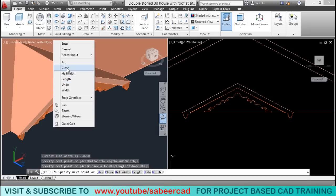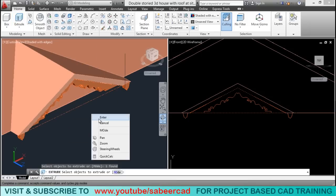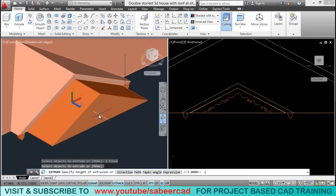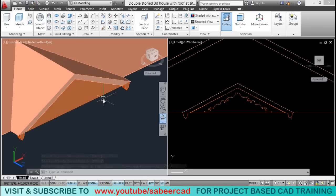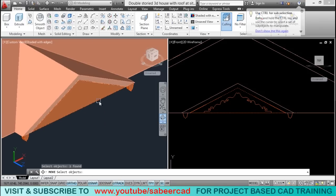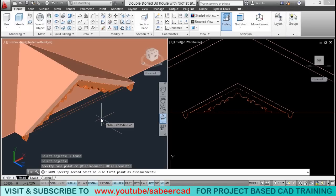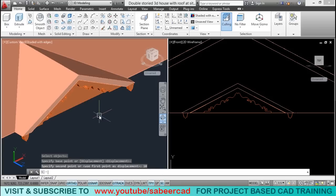Right click and close. Next I'll give an extrude command on this and I'll give a height of extrusion of -5. But this particular object has to be moved inward through the gable through a distance of 10 centimeter so that the decorative work will be exposed. So I'll click on the move command and I'll select this particular object and this is the base point which you can just click on the screen and just keep the cursor in the negative z direction and you type the distance of 10 centimeter.